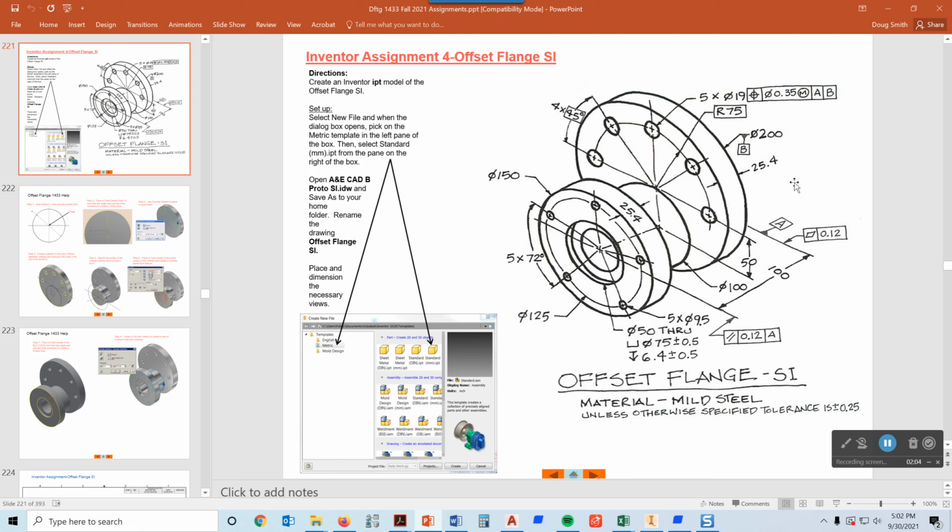Now A is coming in on the back side of the part, so that would mean that we would have an inspection plane in the back that we would put this part up against, and that would represent A. So really what's happening here is that the cylindrical tolerance zones should be perfectly perpendicular to A, and then those cylindrical tolerance zones are located relative to B, and here we see B, and what B is, it's the center axis of this cylinder right here.